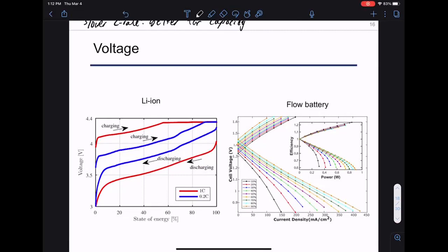So again, all these things are related, right? To do this, we need power electronics that can change voltage. Okay, so your buck converter. All your phones and all your computers actually have a buck converter inside, dynamically changing the duty cycle to charge at the correct C rate. Any questions about this?